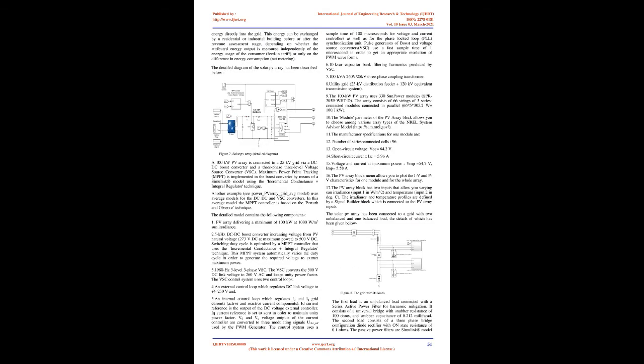Series active power filter. A voltage VF is injected in series with the line and it compensates the voltage distortion produced by a nonlinear load. A series active filter is more suitable for harmonic compensation of diode rectifiers where the DC voltage for the inverter is derived from a capacitor, which opposes the change of the voltage.